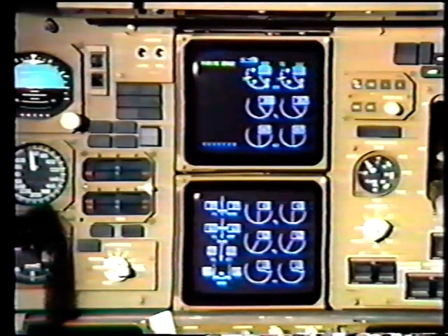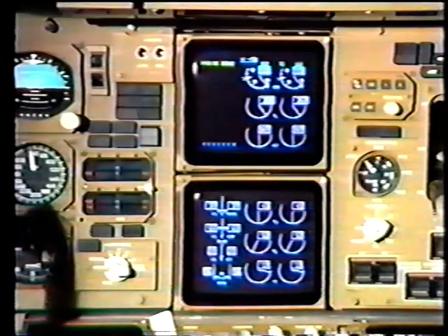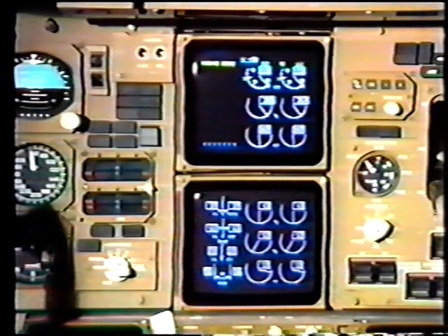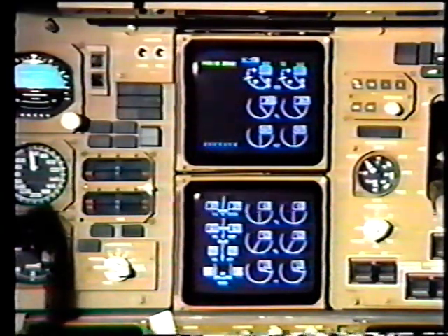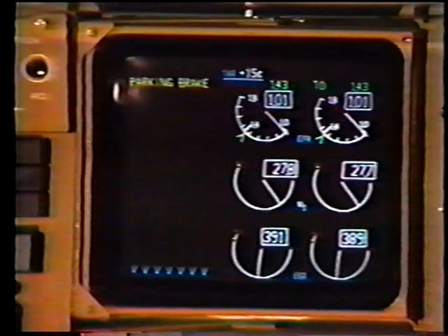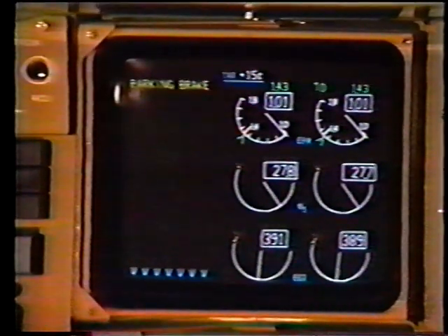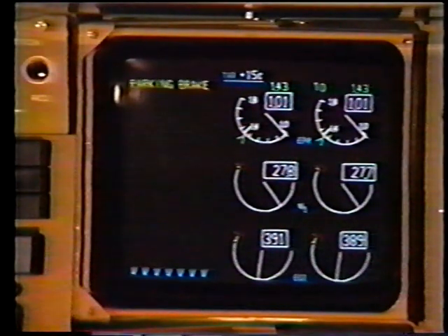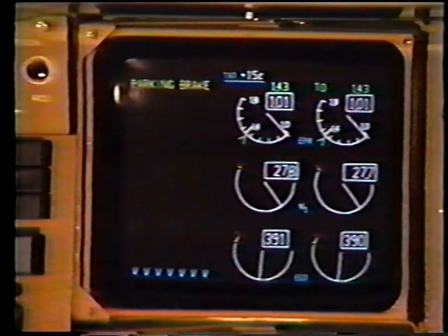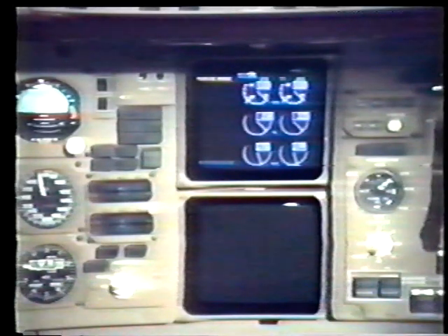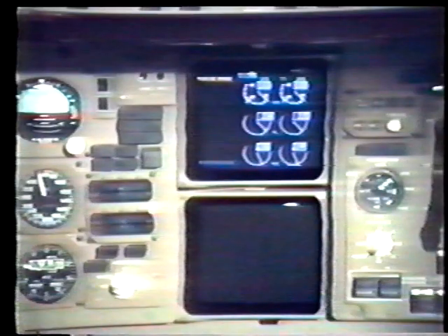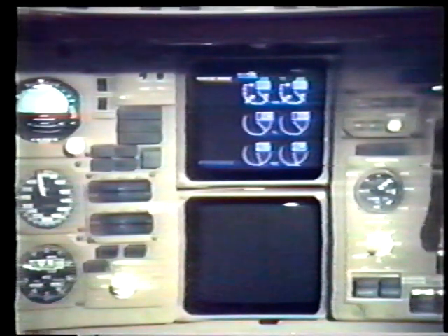To avoid nuisance faults during the takeoff or go-around mode, the automatic display of N1, N2, and N3 yellow band exceedances are inhibited for 5 minutes from the time of the exceedance. A series of 7 Vs displayed in the lower left quadrant of the upper CRT are automatically displayed whenever engine data should appear on the lower CRT. If 7 Vs are displayed and no data appears, a problem may exist with the lower CRT or the ICAS computer.